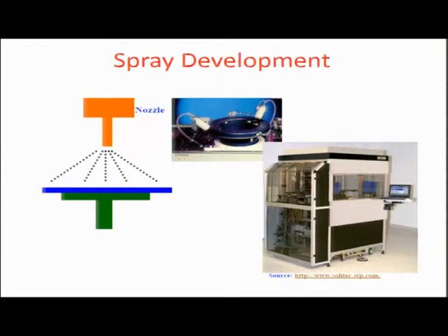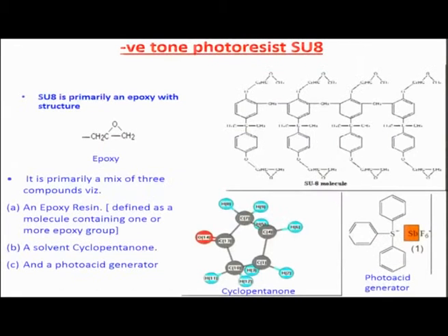Typically in high production systems, the spin coater and the nozzles are eliminated, and so there is a spraying system which will do the job of spraying the resist at a high pressure and ensure that there is uniformity in thickness. And then there are large machines called steppers which are used sometimes for the purpose of high throughput lithography. So, this is how the process is carried out, and these are all projection lithography based systems. Process is carried out in the industry in a very high yield through the following things.